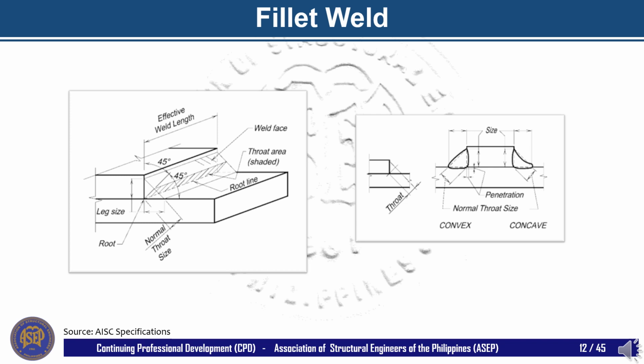Let's begin with the extensively used weld, the fillet weld. In steel fabrication, it is often used to join shear tabs to columns, gussets to beams and columns, stiffeners to webs, and light columns to base plates, as well as many other examples. As you can see in the images shown, fillet welds have a triangular cross-section and are applied to the surface or edges of the materials.